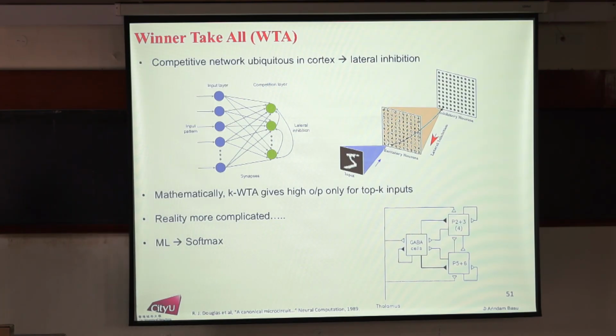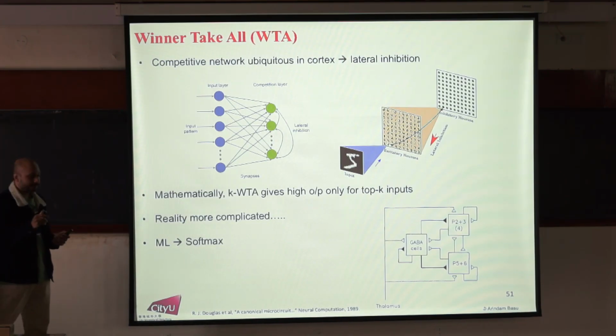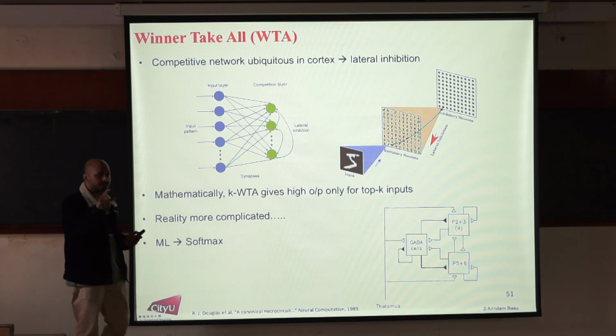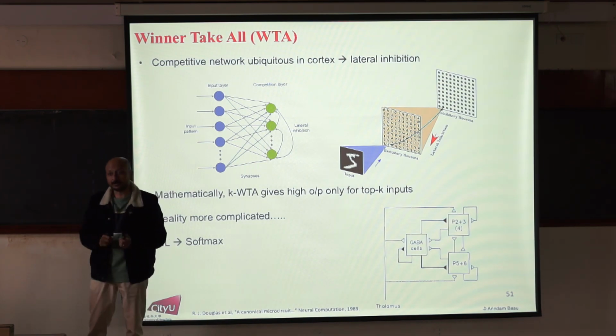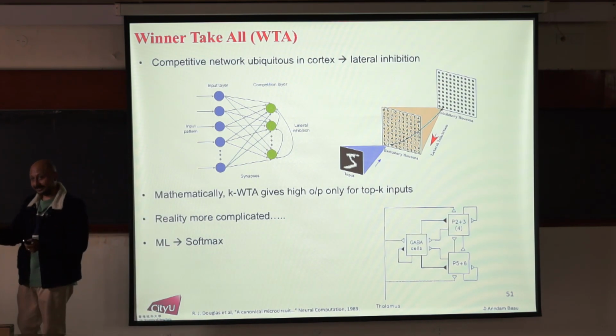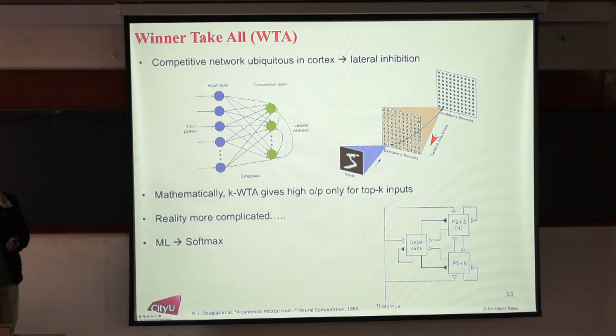Okay. So it turns out people in digital have tried this, and the problem in digital is you have to do a sorting to find out these top k values. That now takes up time, energy. So now I show you an example of how you can do this winner-take-all, sorting everything in memory using the exact same ADC array that I have shown.